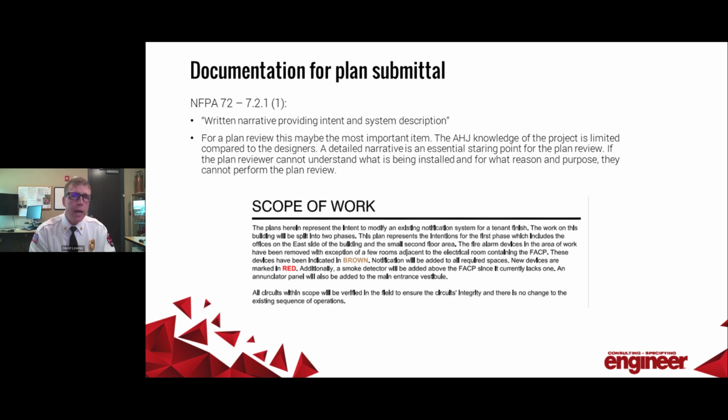But the very first item says that you need a written narrative talking about the intent and the system description, right? Understand from the start that who you're submitting these documents to, whether it's someone like myself, or an insurance AHJ, or maybe even the owner of this building or space, we don't necessarily have the knowledge that you, the engineer and designer of this system, have, right?